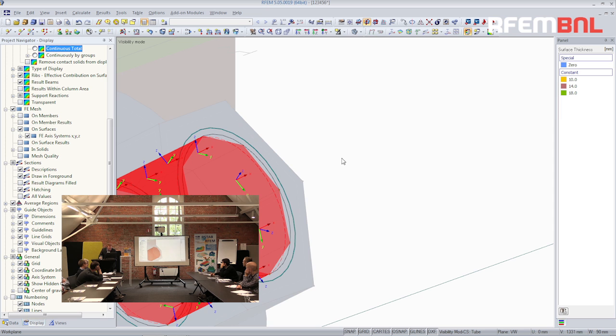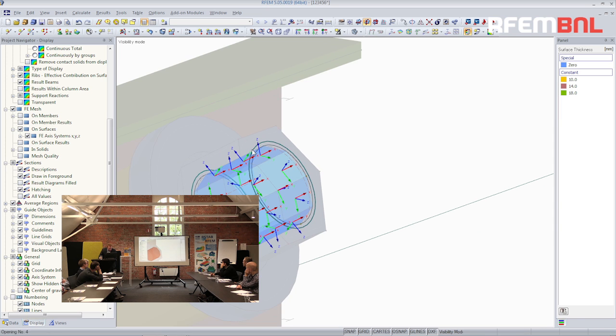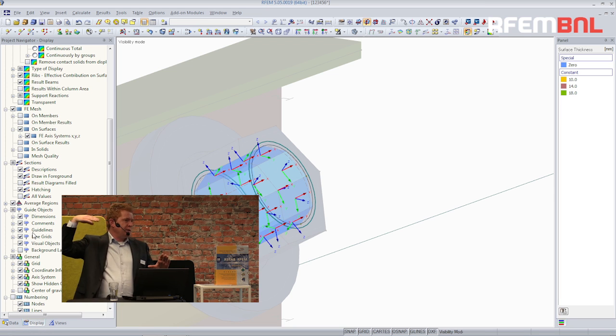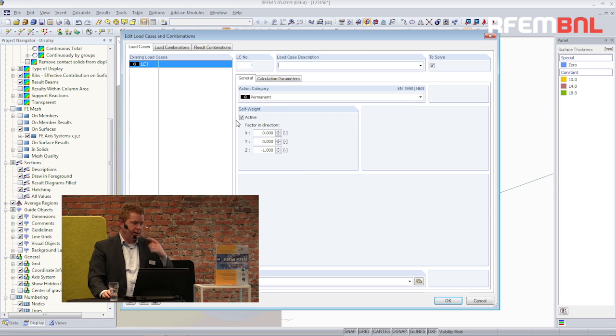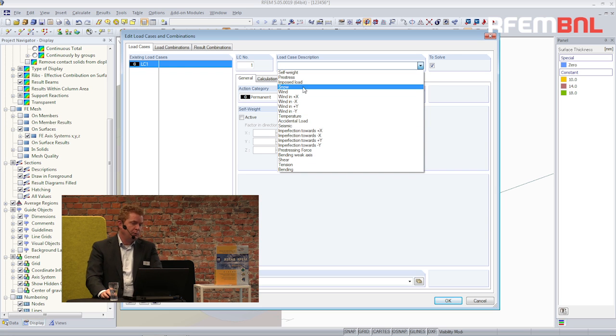And you see here that the x direction is in this direction locally. So it means that if you apply the stress in the minus x direction, it is applied in the correct way. This is what I always do when I apply some load to a surface for solid modeling.